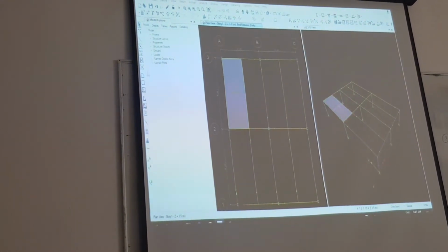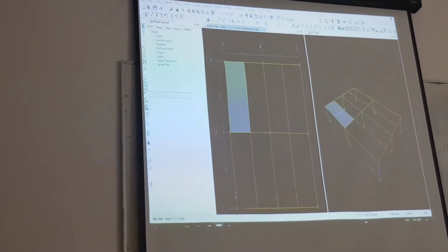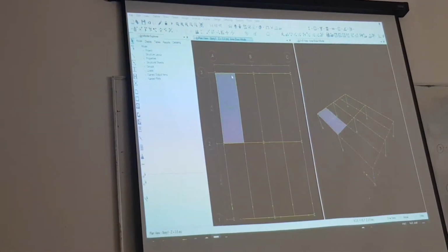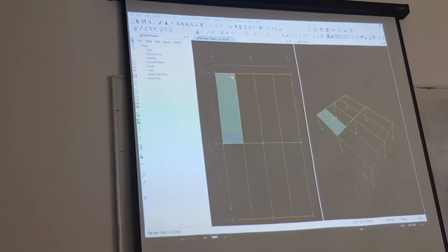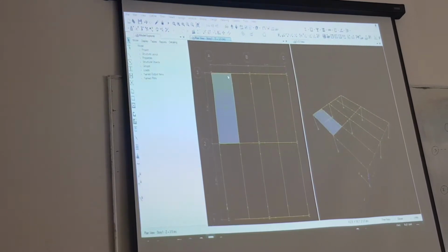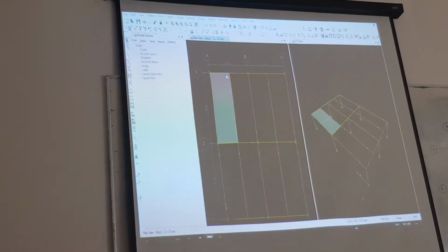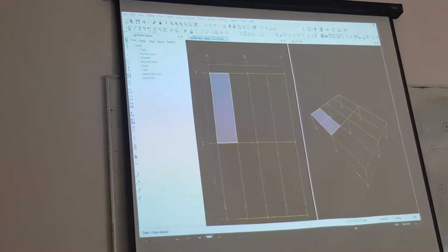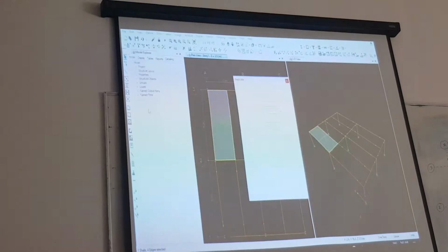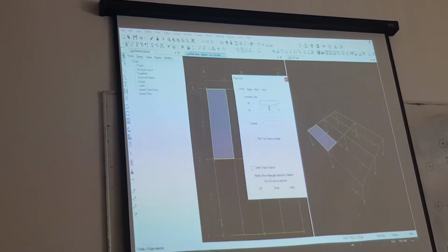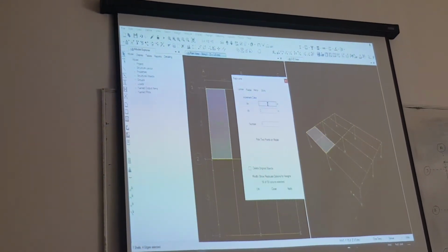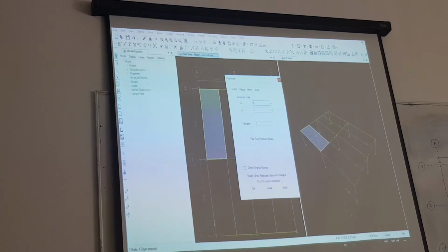Okay. Now you have to apply throughout it. Now we are going to draw all these particular slabs. As you know, if you see that all these dimensions are symmetrical, simply we can replicate them, right? So how can you replicate them? Click on the first slab, go to edit, and there is one option called replicate. Click on replicate, and since we are going to replicate it in x-axis, let us say 3 meters.